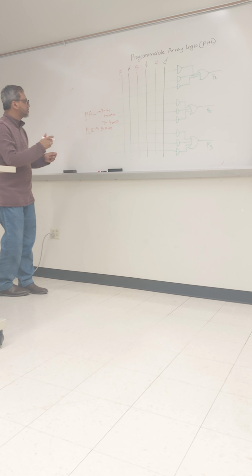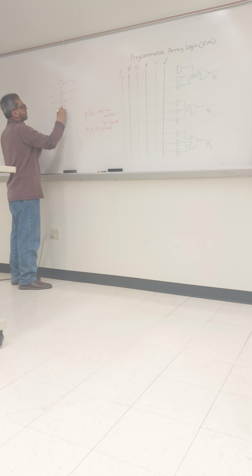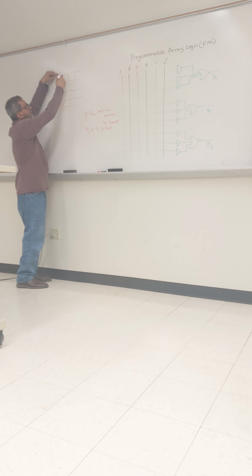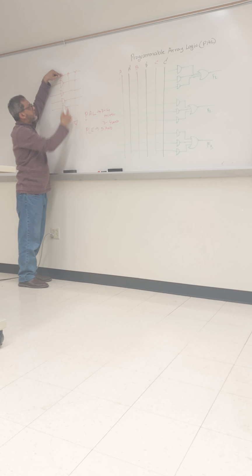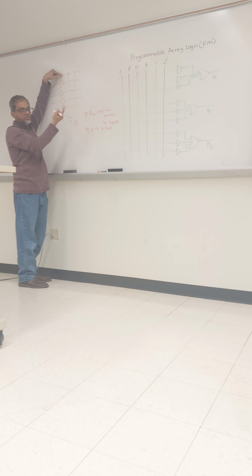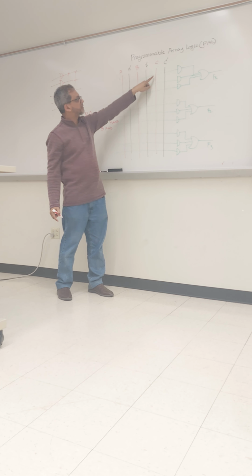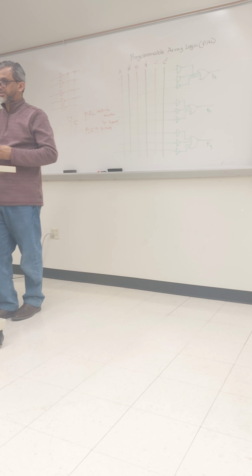In our previous lectures, the AND gate arrangement was something like this. If you remember, I drew a little bit, not the whole thing. Then we take 2 OR gates. Here this is the minterm, and these minterms can be shared with both OR gates. If you need these minterms, I can share them with both OR gates. That's how we used it. But here, we cannot share the minterms. These minterms are given only to this one. We cannot share, so this is kind of a disadvantage.